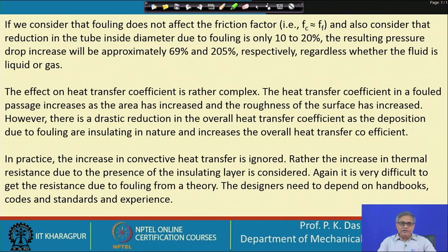Which heat transfer coefficient? It is the convective heat transfer coefficient which will increase. But is that then a boon, that fouling has taken place and the heat transfer coefficient has increased? Not at all, because the foulant which deposits on the surface is highly insulating.